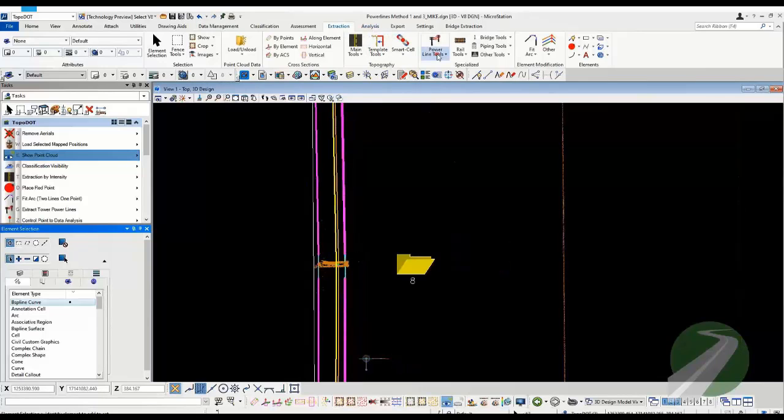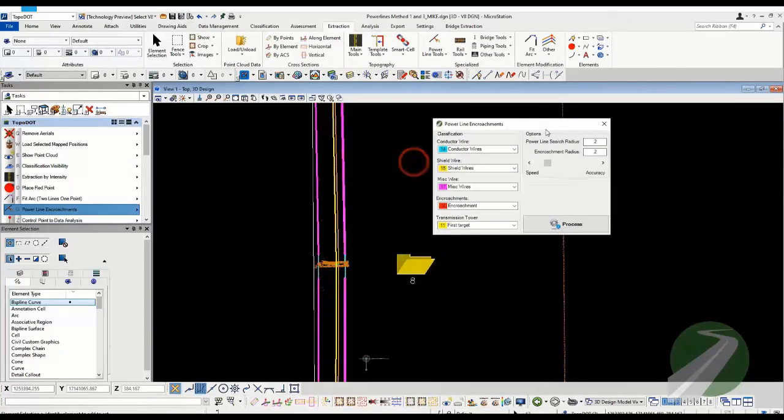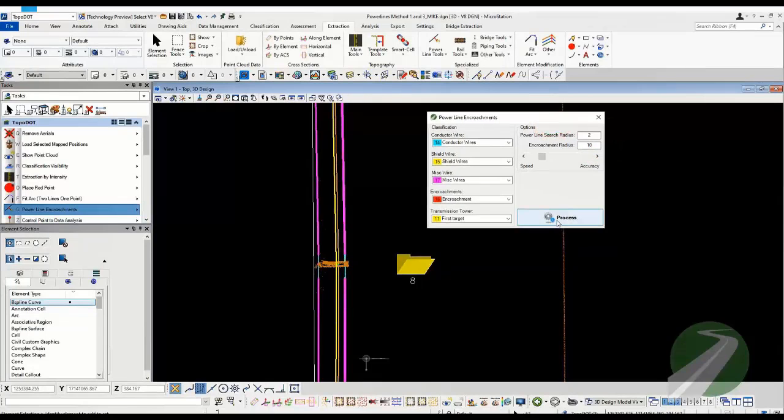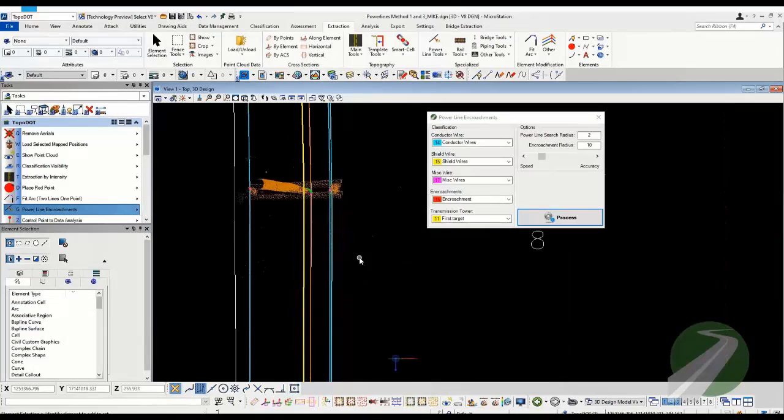All right, so now I'm going to be going into classification. If you notice, I selected my conductor wires, but I only selected the B-spline ones. This is just in the span. The reason for that is some of these wires kind of float around a little bit. They're a little bit fuzzier within the span. So I'm increasing my search radius for those wires.